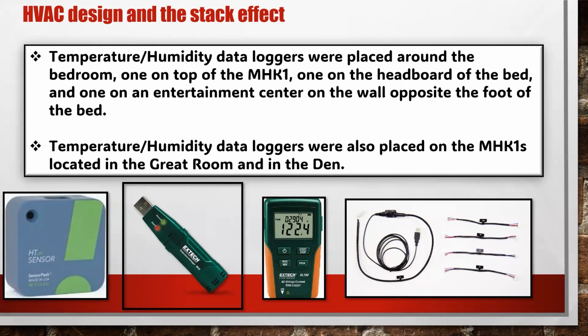Everyone is afraid of undersizing it, in many cases forgetting all the other loads in the house are heating the house. Our heat loss calc that we do is based on nobody being in the house and everything being turned off in the house.